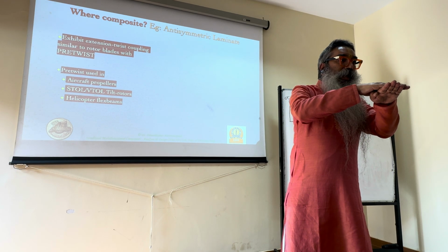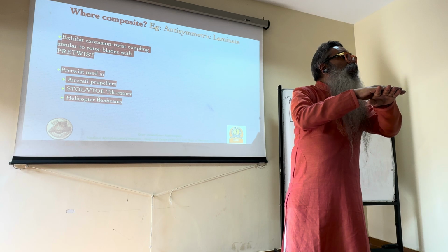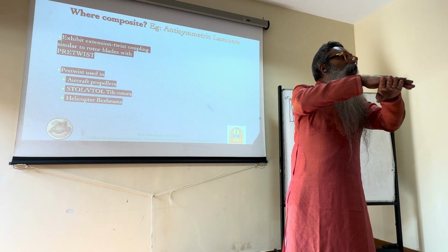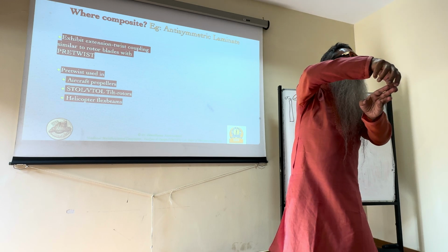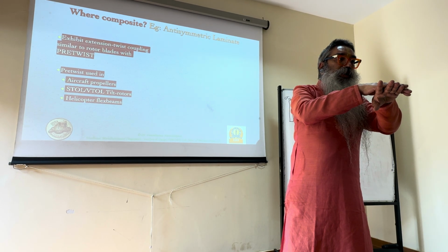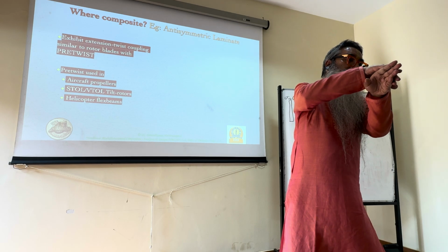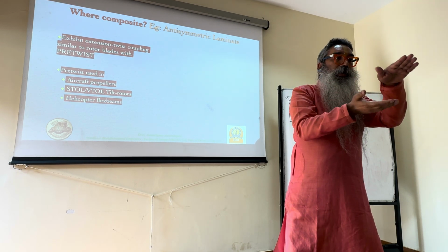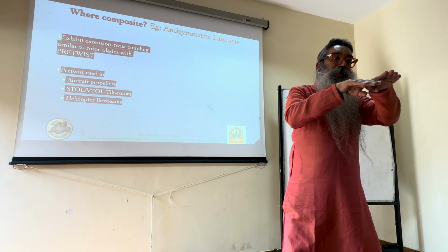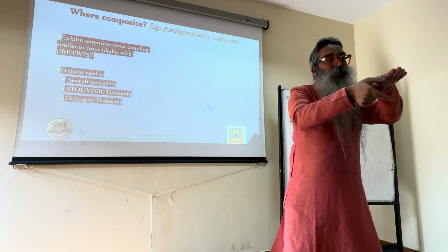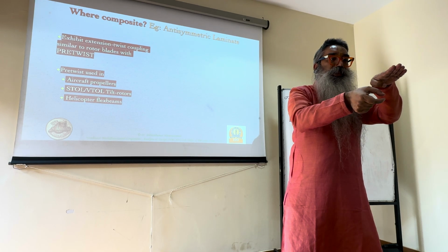So now this acts almost like a pre-twisted beam, because if I try to pull this, what happens is this tries to straighten out, which also makes it kind of twist, right? So this kind of combination of manufacturing with a certain pre-twist and then having about the mid plane, at any given distance, if you have, let's say, 30 degrees, at an equal distance over here you have minus 30 degrees of the same thickness.